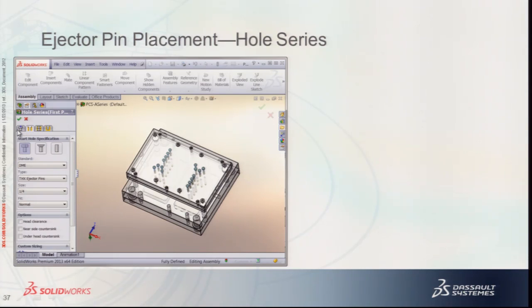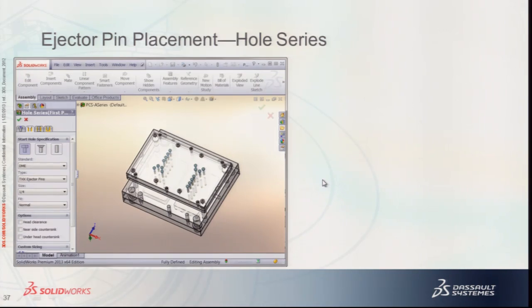The first tab is essentially your sketch. You place your sketch based on maybe some holes in your insert that you've put for your ejector pins, constraining them, and then you have some options in the hole series. The second tab is your middle sections, and the last tab is your end component. Hole series is used for if you're bolting a bunch of plates together, so you have the option between a threaded hole or a through hole. We hit through hole because we're doing ejector pins, and then we pick that B plate as our end plate. That makes a nice hole.